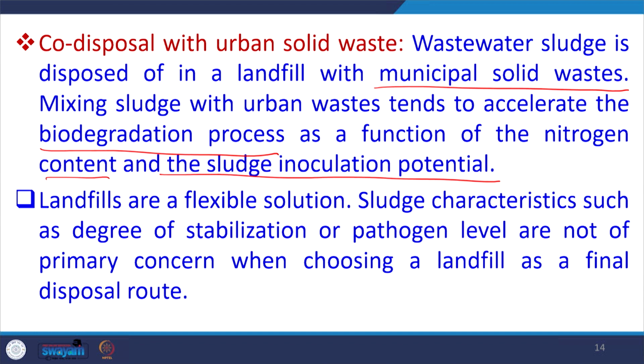Sludge characteristics such as degree of stabilization and pathogen level are not of primary concern when choosing a landfill as a final disposal route. Okay. If we are going for incineration also, again ash has to be disposed of, but the amount of ash is much lower as compared to the sludge itself. So, if a landfill is used, it can be used for a very long duration.